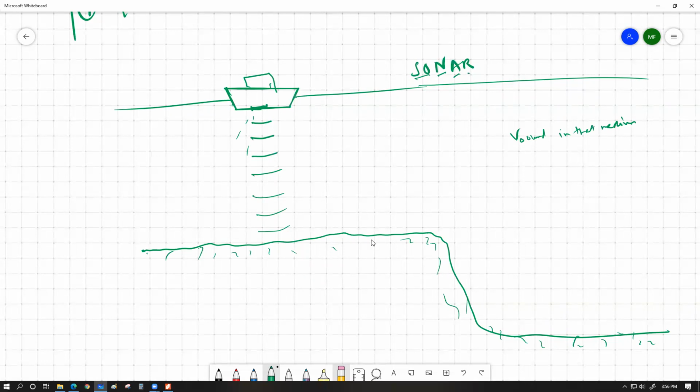Known from earlier means experiments had to be performed on different amounts of specimen, and the average speed of sound through that medium at the temperature the device is supposed to operate at should be fed into the device's calculation mechanism as a constant so that we can use it for our calculation.